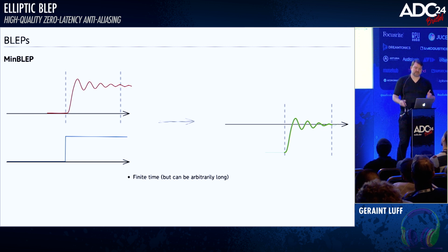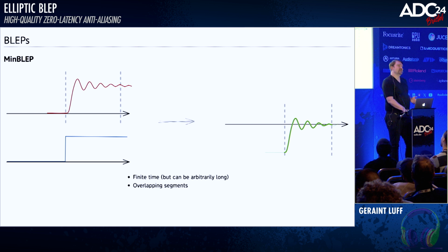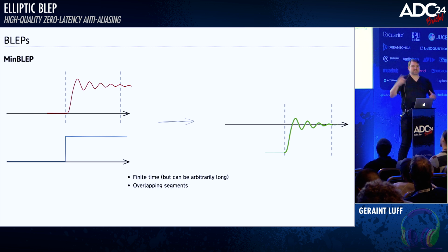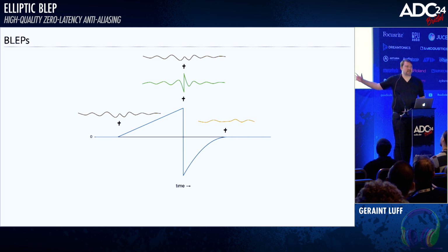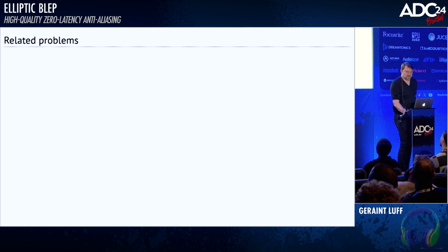to make the impulse response longer. You still have that problem with the overlapping segments and the bookkeeping, and because this is generated as a table, generally then you'll do this sort of polyphase implementation, which again, it's fine, it's fiddly. But yeah, this is generally what BLEPs are. Hopefully that makes sense as a technique, these anti-aliasing stamps that we're sticking on.